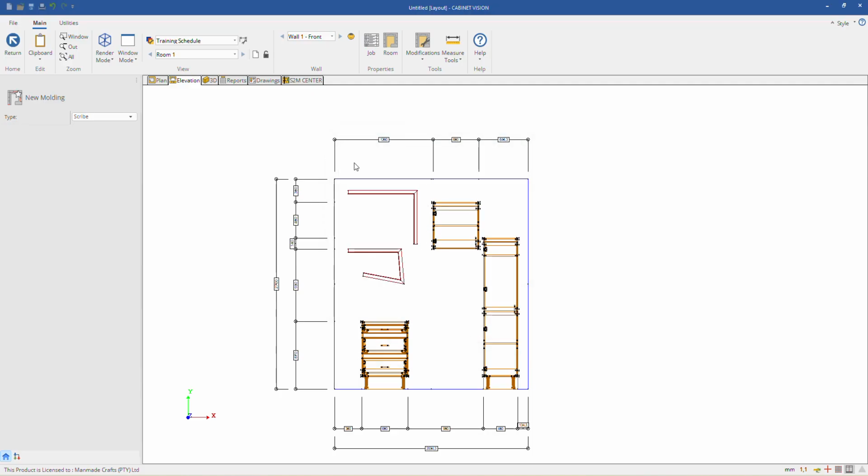So having an understanding of this is critical, because if you don't understand this, you're gonna call me every 2 days. Oh AJ, listen, I can't find this. I don't know why my basements aren't showing. Why aren't my interior parts showing? Why isn't this showing? And I'm gonna redirect you every single time. Layers. Go check in your layer schedules if that item is switched on and if it's set to be viewed.